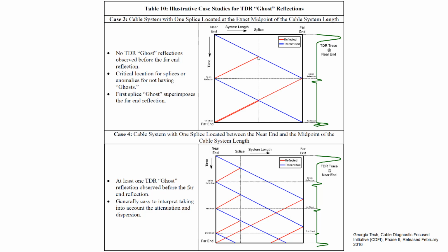Now what happens is, this first one, there is a reflection here due to the joint, but this comes back, and from here the signal originates again. It again gets reflected at the near end also, but it is given in blue color because it is going in the forward direction. So it comes here and again at the joint it gets reflected again. So at the middle point you have only one splice reflection clearly visible, but the far end waveform gets modified due to the combination of both. It will not be a simple summation of these two. Actually, there will be a slight difference in the far end signal which comes out here. But in between there are no ghost reflections that you can see. From here to here, there are no other reflections other than the joint here.